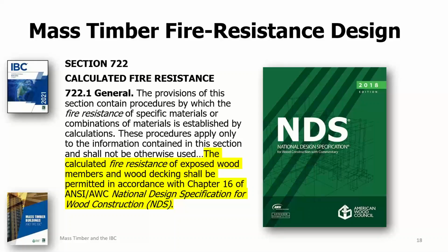Here's the actual code language from IBC section 722.1, which deals with the calculated fire resistance. As you can see in the highlighted portion here, Chapter 16 of the NDS is the reference standard that's given for calculation of fire resistance for exposed wood members and wood decking.